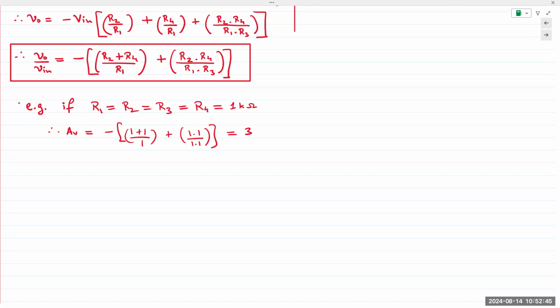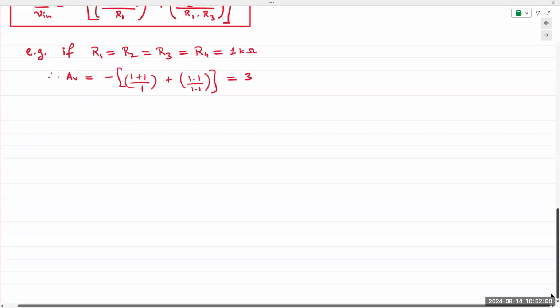Also, the case in point that I made earlier before I began this example was, if we wished a larger gain, like say 10 or 20, and we had a large input resistance, R1 is large, then R2, the feedback resistor, goes to like 20 times that input resistance.